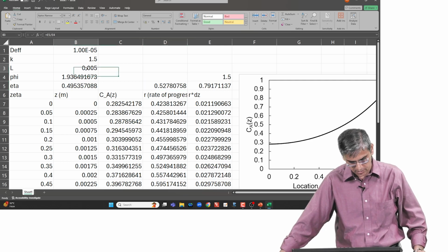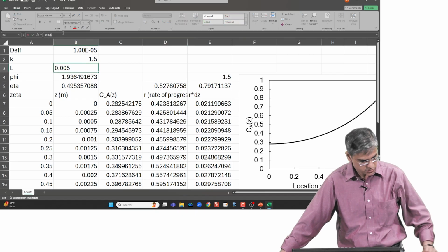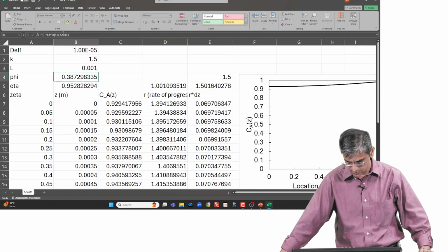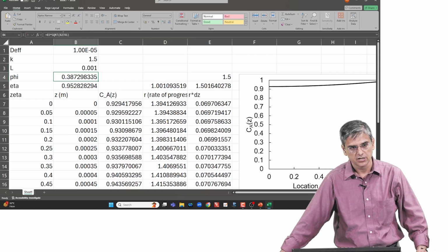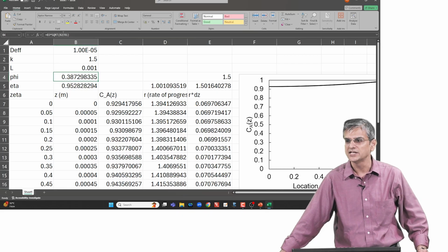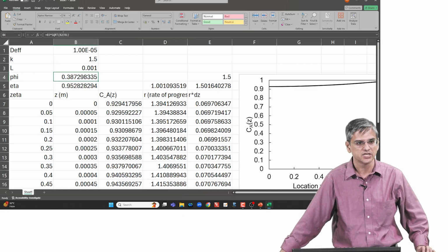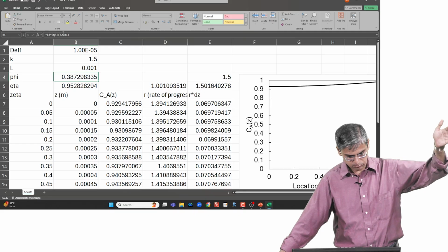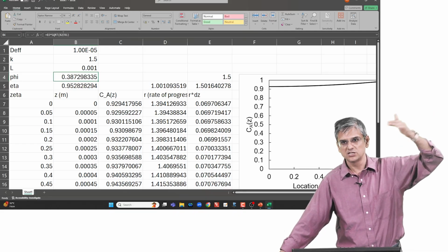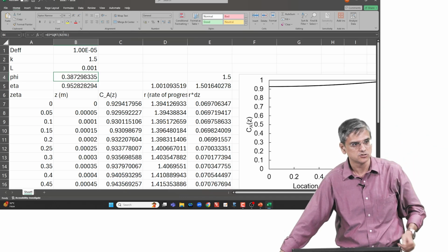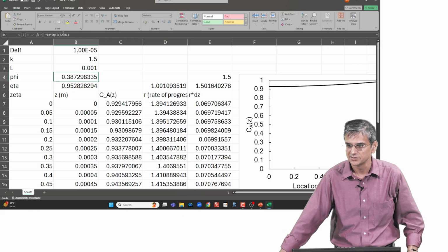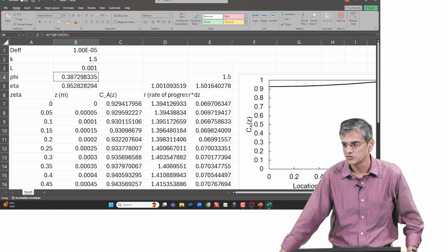Okay, and if the thickness of this was equal to 1, net reaction rate is 1.5, eta is approximately equal to 1. Okay, why is this mistake? This mistake is because of numerical errors. The actual calculation should be first value divided by 2, last value divided by 2, and all the middle values multiplied by 1. Okay, if you know your trapezoidal method of integration, right?